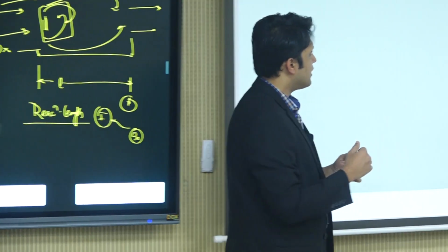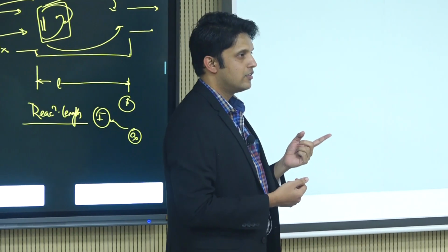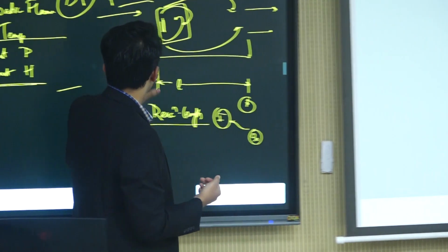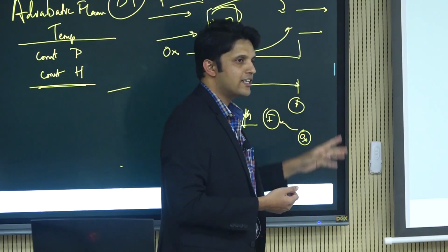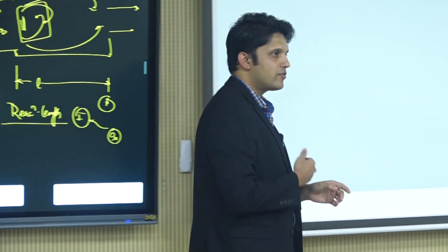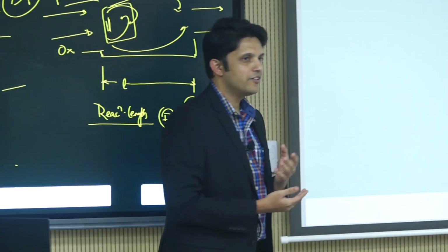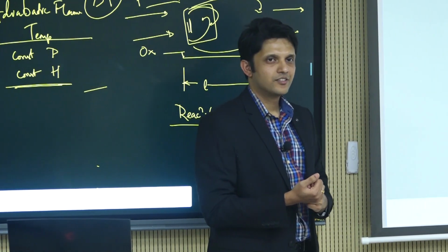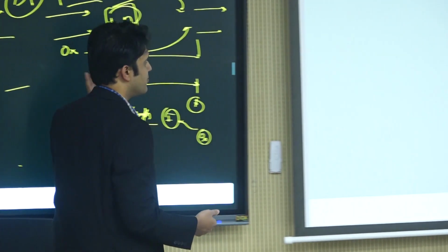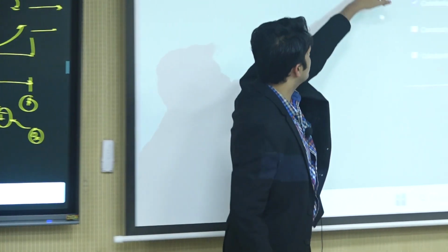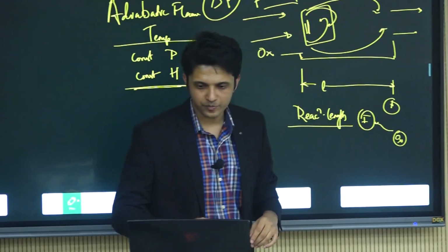Just reminding, if you want to calculate the enthalpy of reaction, what kind of process should we have? For the enthalpy of reaction, your fuel and oxidizer go in at standard reference conditions and come out at standard reference conditions. So what is that process? Constant temperature and pressure, because the reference conditions are maintained. So you select constant pressure and temperature, and you can simulate these various processes.